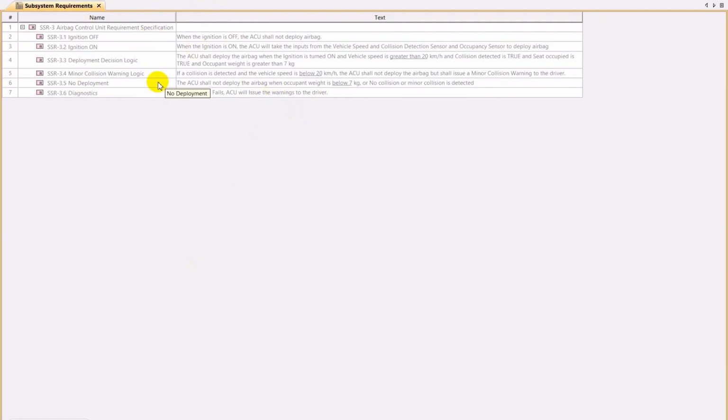With system behavior validated, we now write the subsystem requirements for the controller unit. We have around 7 requirements defined for it. But to ensure that these requirements are correct, complete, and consistent, we validate them using the stimulus tool. Stimulus checks the logical correctness of the requirements and confirms whether the specified behavior meets all conditions without conflict.